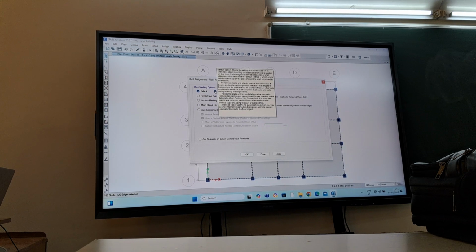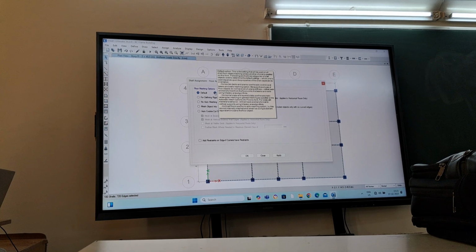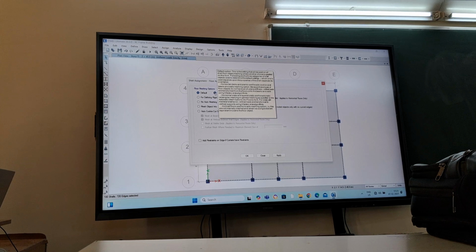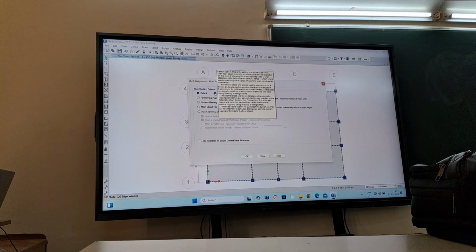This is the setting that will be used on all shell floor objects unless another choice is specified on this form. Following are three categories of shell objects used to determine the default settings. Which one is used depends upon the properties of the shell object and its orientation.